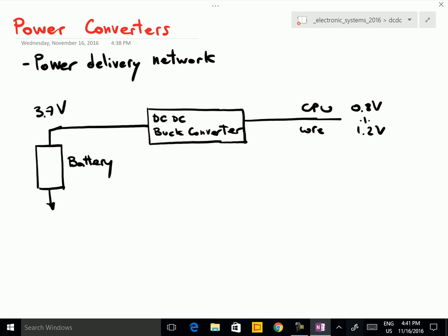In order to save power, the supply voltage and the clock frequency of a microprocessor is tuned on the basis of the load of the microprocessor. So if the load is large, then one has to increase the clock frequency, and also in that case one needs to increase the power supply. But when the load is small, then it is possible to decrease the clock frequency, and therefore one in that case can also decrease the supply voltage.